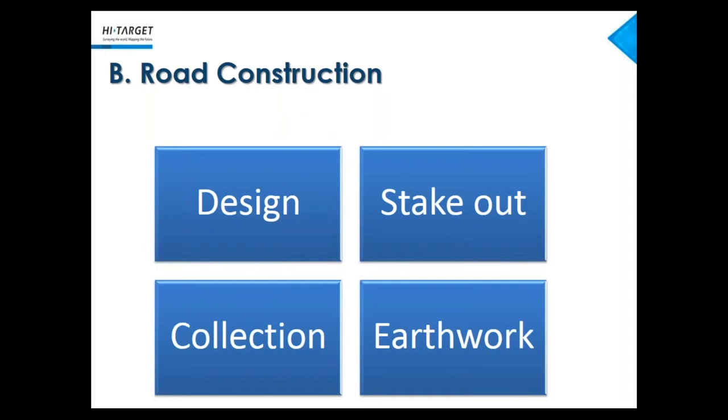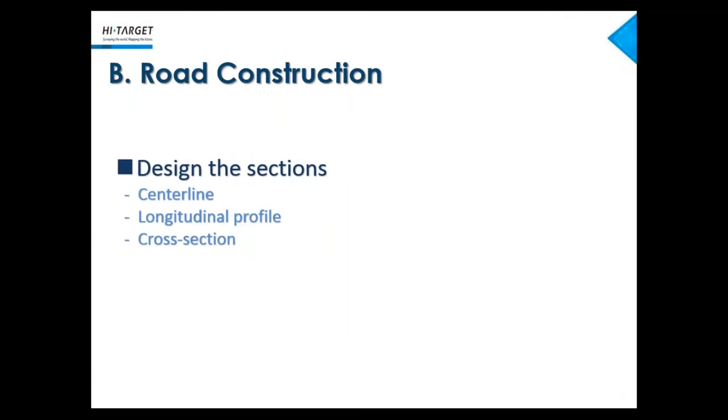And also you need to calculate earthwork, either to fill or to cut. So when we design, what we need to design is the sections for the center line, for the longitudinal profile, and the cross section.